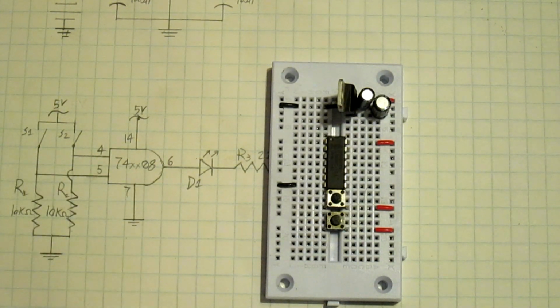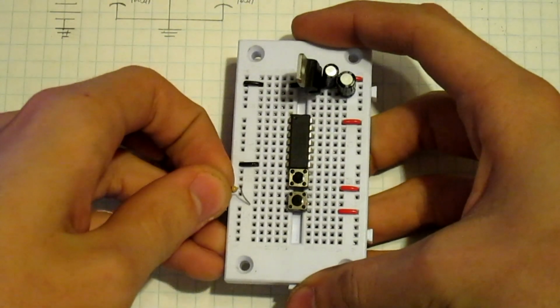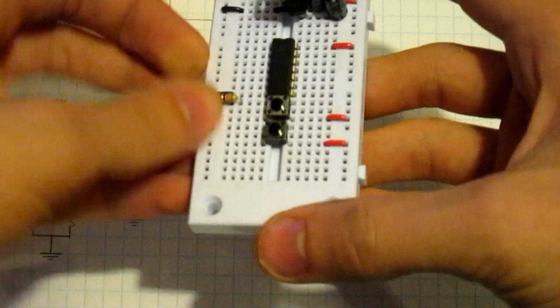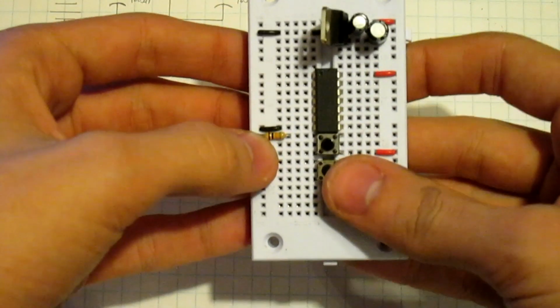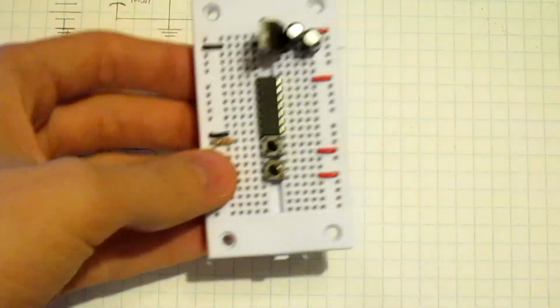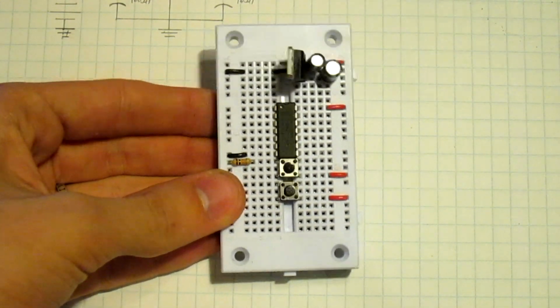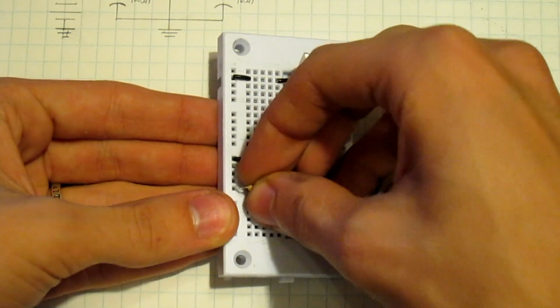What it does is it sets the default condition of the AND gate. If you just leave the inputs alone, you don't give them a 1 or a 0, you don't connect it to 0 volts and you don't connect it to 5 volts, then bad things happen. It can't make up its mind what to do. And so we need to insert these resistors. These are brown, black, orange, gold resistors, which means they're 10k ohm resistors, and the tolerance, or how accurate that rating actually is, is plus or minus 5%.